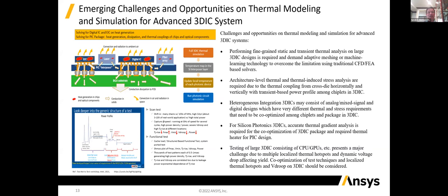including the silicon photonic system, where the thermal heater design is very important for the PIC. So here we need to solve the thermal environment surrounding the PIC in the interposer. Once we get the temperature, then we can calculate the waveguide and the laser property using the simulation again. And the thermal heater is very sensitive to the waveguide property for the resonance, which has a property of plus minus 1 degree. So it's very important to see how you design the thermal heater effectively for the PIC design.